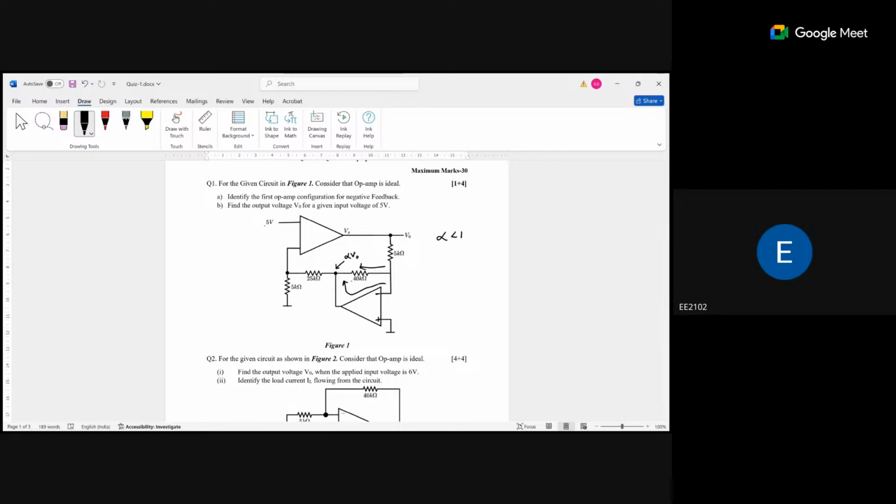When we go this way through the operational amplifier, this is the input resistance and this is the feedback resistance. Because of the operational amplifier, we get minus RF by R1 into V out. So we are getting minus beta times V out because of this circuit.